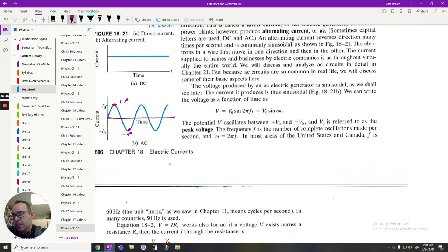Now, a couple of things to keep in mind. First, it's called a root mean squared, which is the square root of the average of the squared values. So first thing we do is we square all of the values. That removes any negatives from the problem. Think of it a little like reflecting this curve up here. It's not quite the same thing because they're squared, so they're bigger, but we've adjusted the values. And then we average them, and then we take the square root. It ends up putting us somewhere around here.